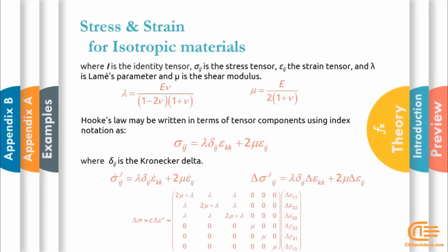Note that if you use a subroutine for the material, you can't use any of the properties of the material, such as plastic or damage or anything else, in the software's user graphical interface. And Abaqus ignores any value you enter in the property module in the create material dialog box. Well, it's time to move on to an example of isotropic elastic material.